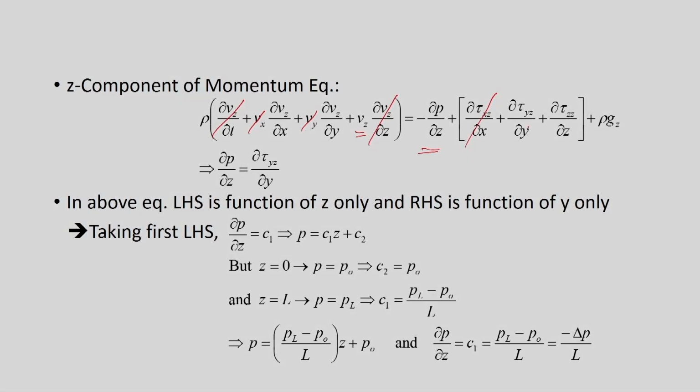Here in tau yz, Vy and Vz are existing, and then Vy is 0, and then the Vz term is a function of y. So, this term will be there. So, we cannot cancel it out. Because of the fully developed flow, ∂/∂z of velocity terms, shear stress terms etc. would be 0. So, the last term ∂/∂z of tau zz is 0 here. The last term is rho gz, that is the gravity term, is not existing. So, that is also 0.